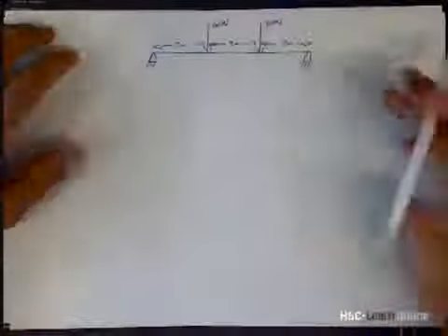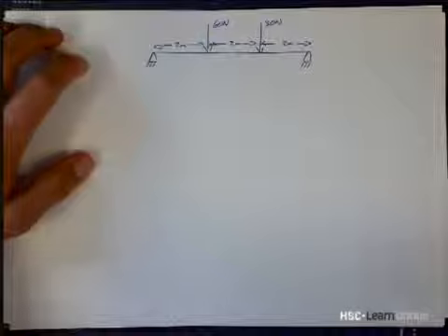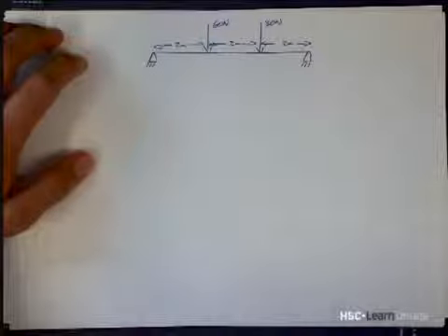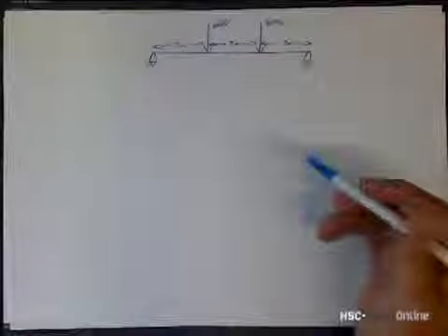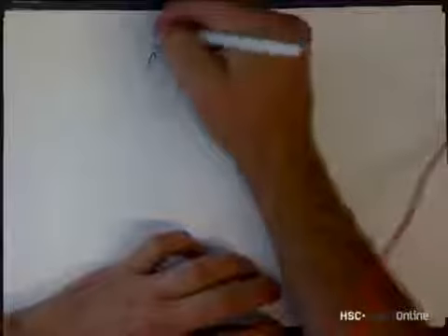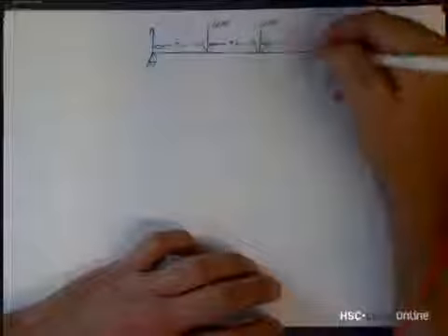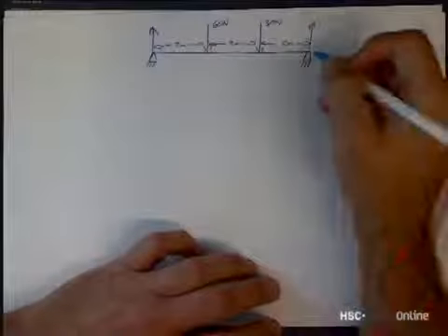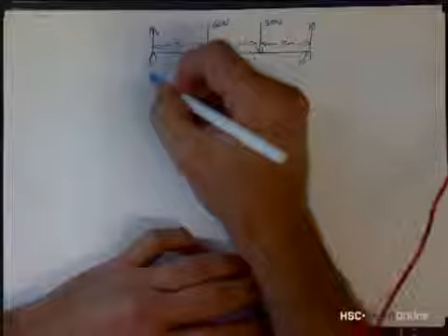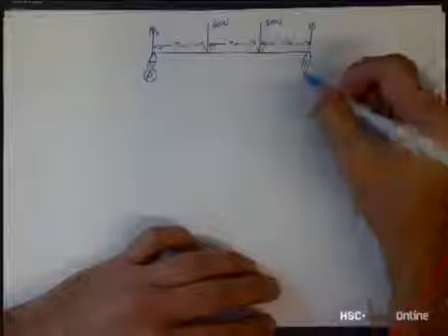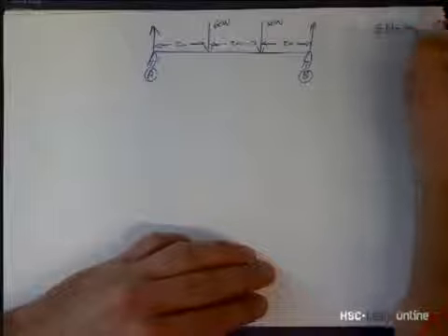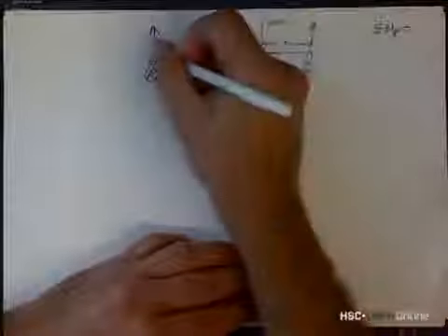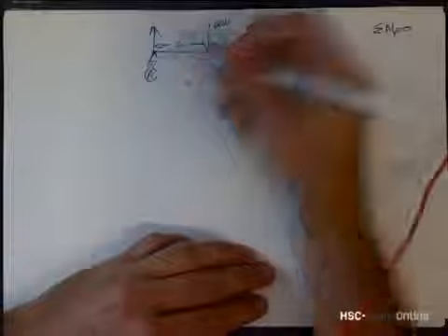The first thing you normally do with these kinds of calculations is draw force lines through all your forces. The starting point, as with all of our calculations, is to calculate the reaction forces at A and B, and to do that you take the sum of moments equal to 0 around point B, starting at A, and then do your calculations.